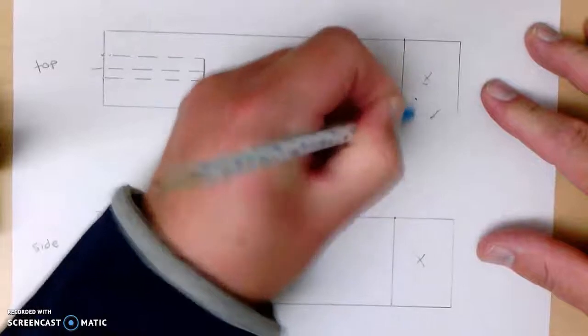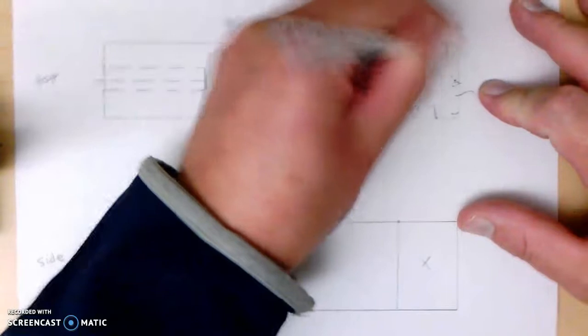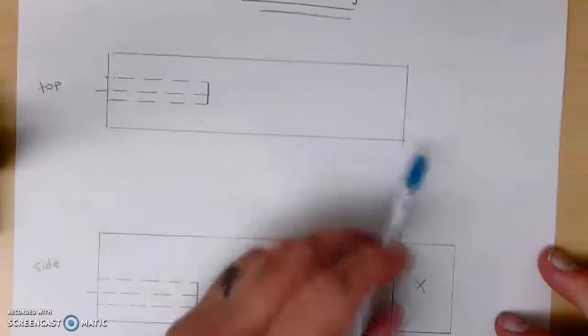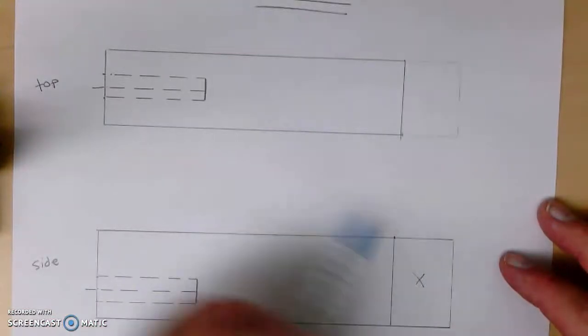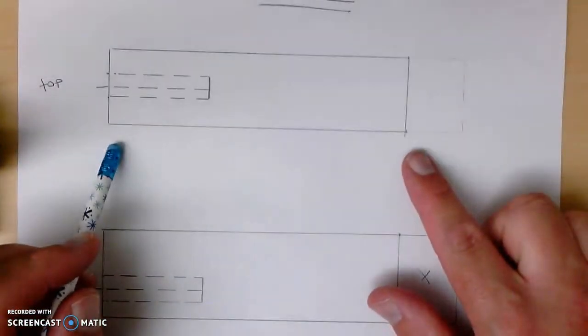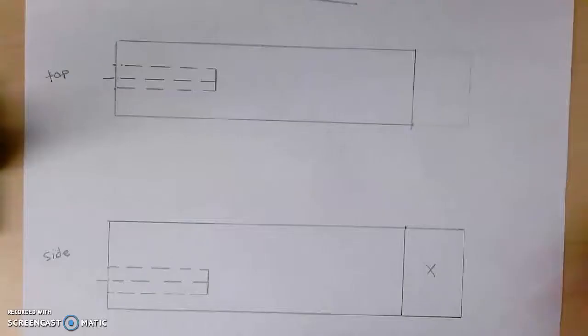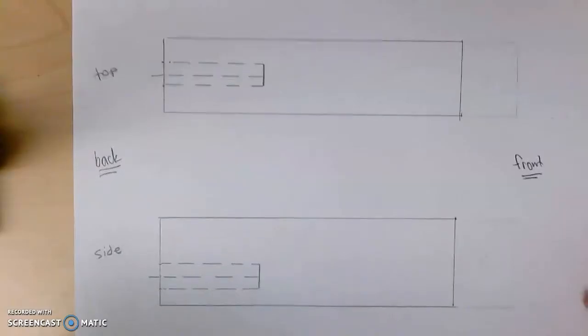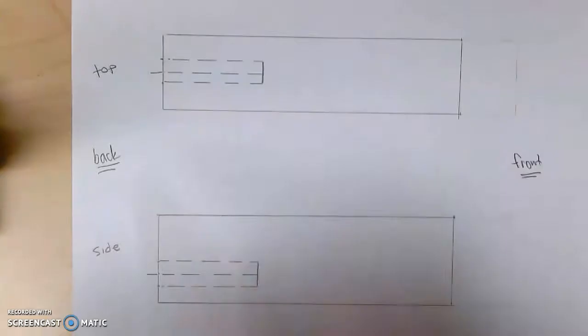Okay, so if you are changing the length of your car, pause the video right now, change the length of your car, and then erase those lines that are not part of your car anymore, because I'm cutting off that 1.25 inches right here to make my car a little bit shorter. So go ahead and pause that video and measure what you want the length of your car to be, somewhere between 6 inches and 7 1/4 inches, and then erase the parts that you don't need. Alright, you can see that I have erased the top and the bottom, the part that I don't need, so this is now 6 inches long.